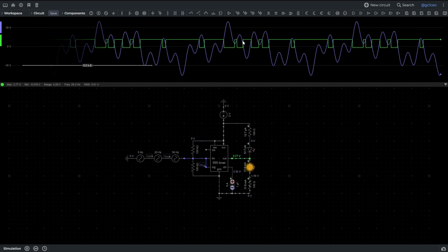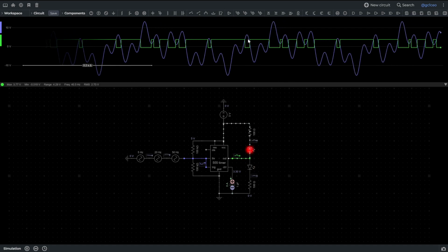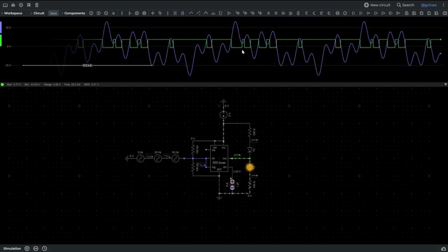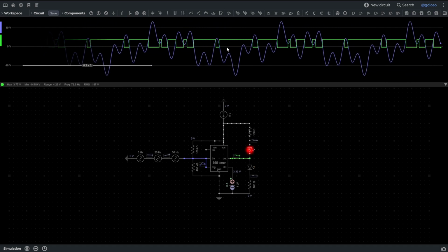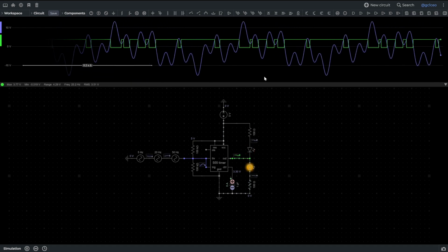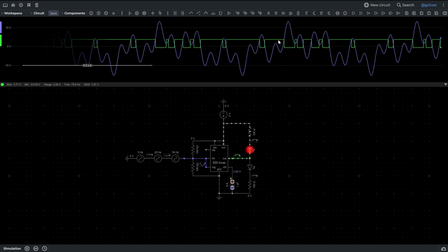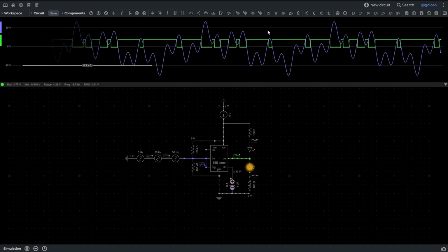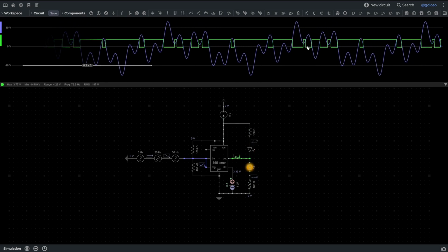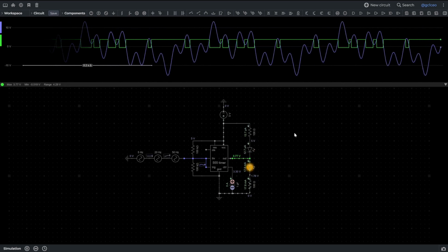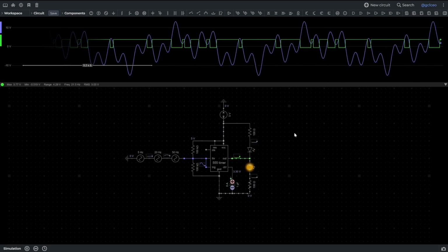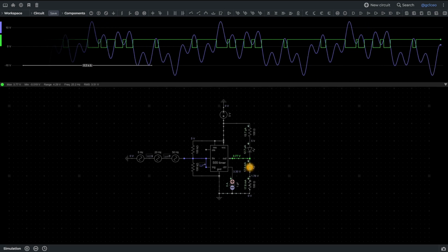But you'll notice it only goes to an upper when it hits a certain point in the analog signal, and then it only goes lower when it brings it back down. It's not going to respond whatsoever to negative voltage, purely positive. So all of this stuff from zero downward is completely ignored. Anything that goes above the upper threshold is going to be ignored as well. So yeah, in a way, this is converting analog to digital in a very basic way.